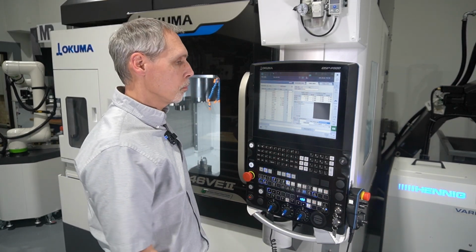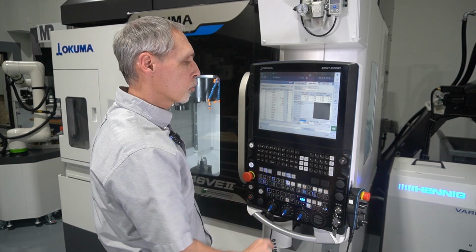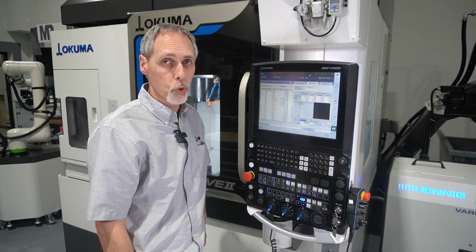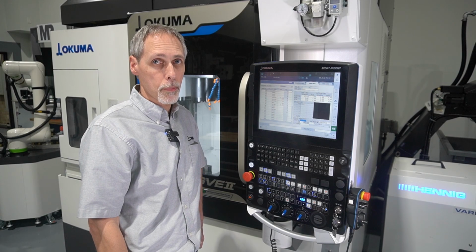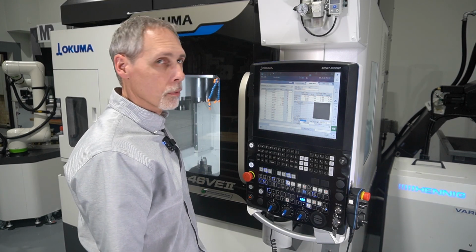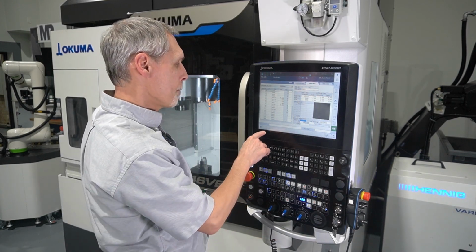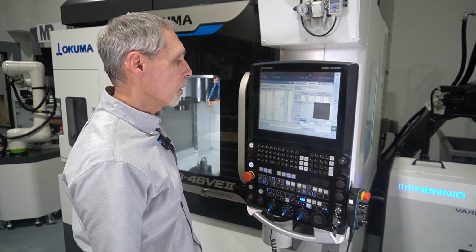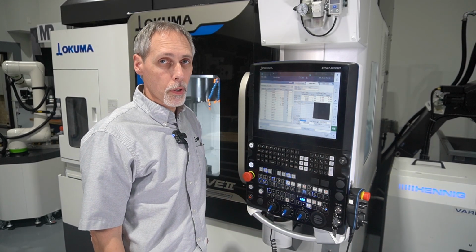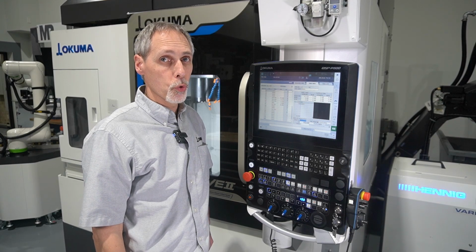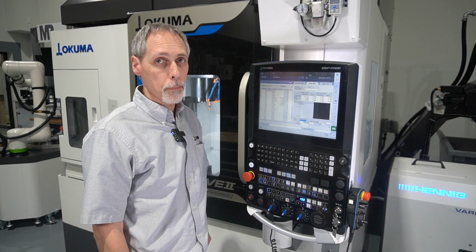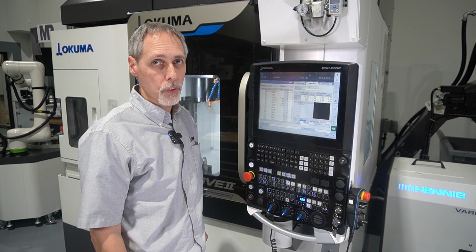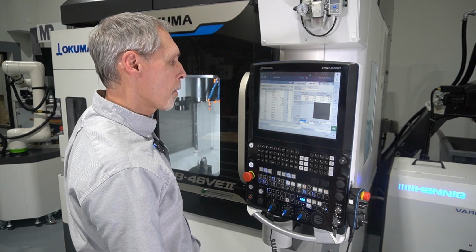Once I do that, I'm assuming I'm using groups here. If I don't use groups, then I can use this with one tool and it'll just alarm out once the time has expired. But I want to set up groups for this example. So we're going to set it to group number 1. Anything with the same group number is going to be treated as the same tool. So those need to be the same type of tool, same dimension, size, style, all that. It has to be the same tool.